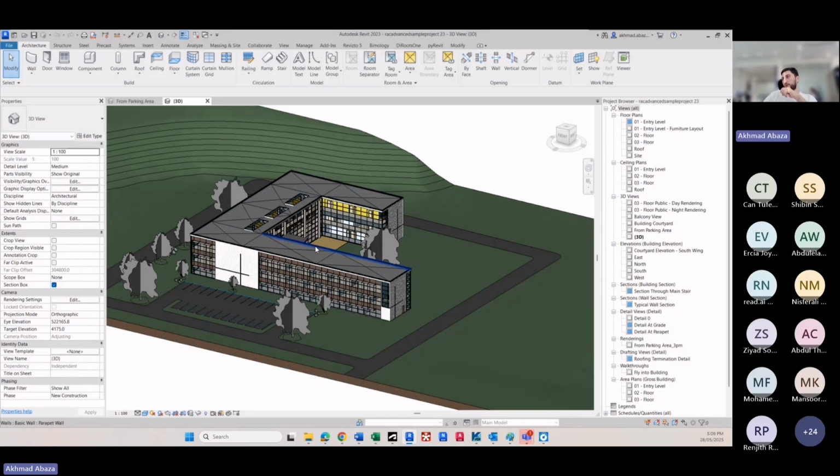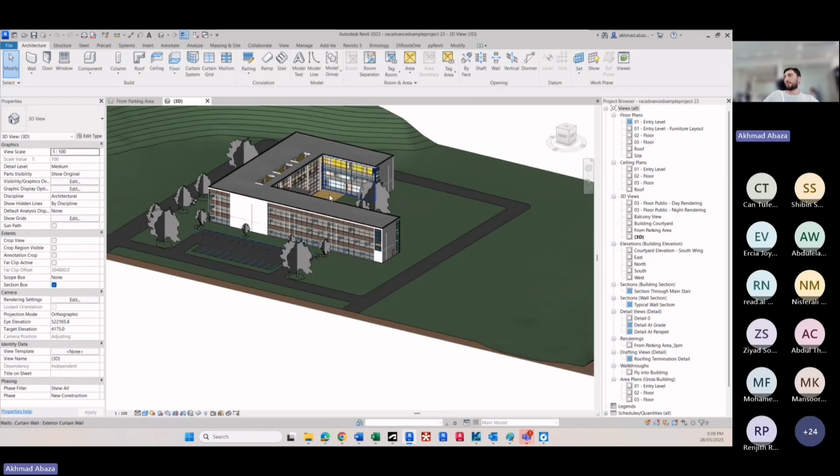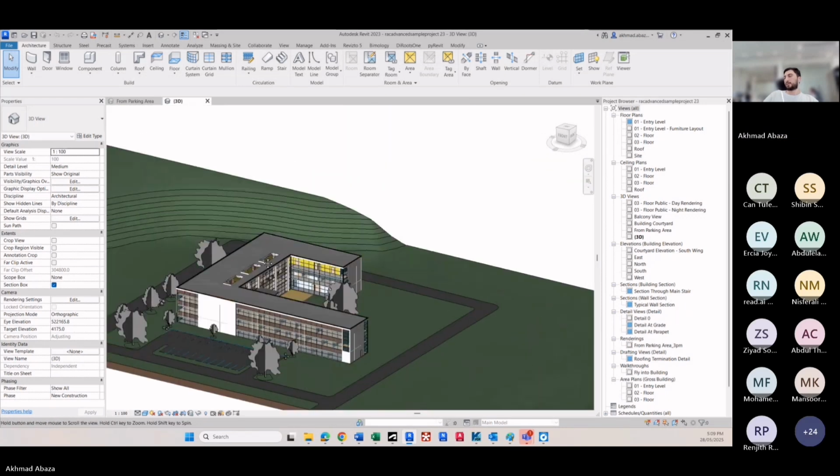The other most important daily zoom thing you need, or let me call it orbit. You will press the scroll button along with shift. So if you see that the indicator of the mouse changed, if I only press the wheel button, it's like a pan, same like AutoCAD.